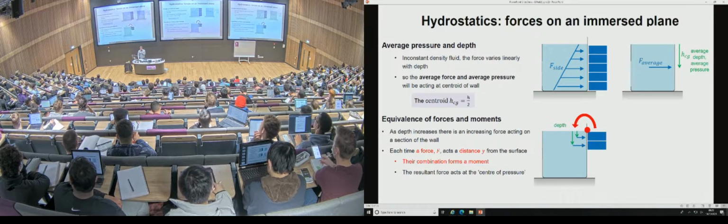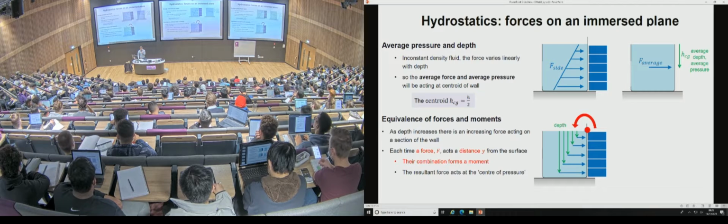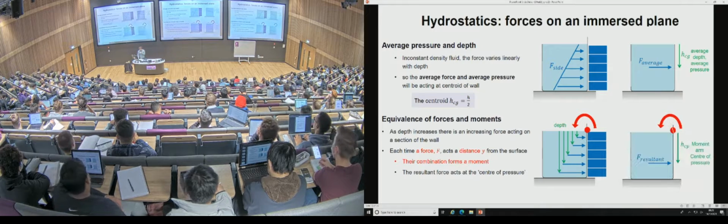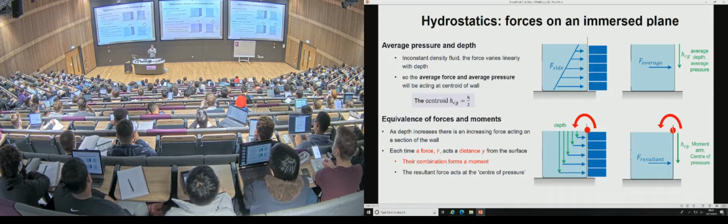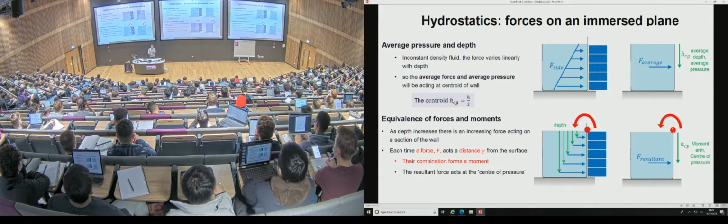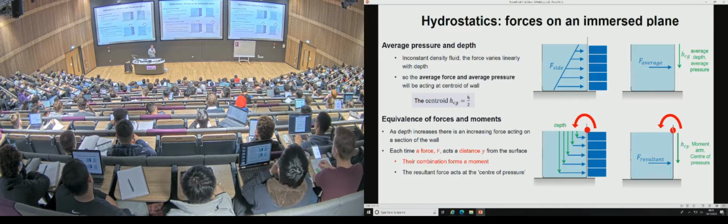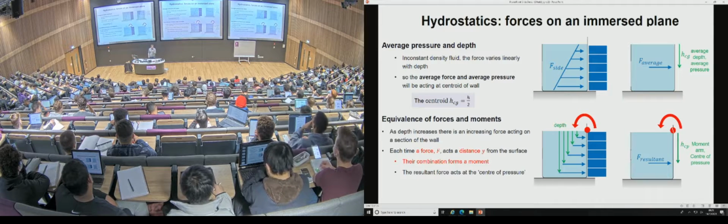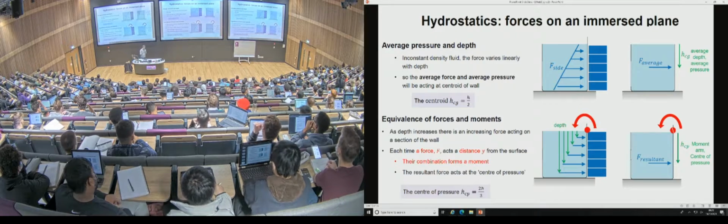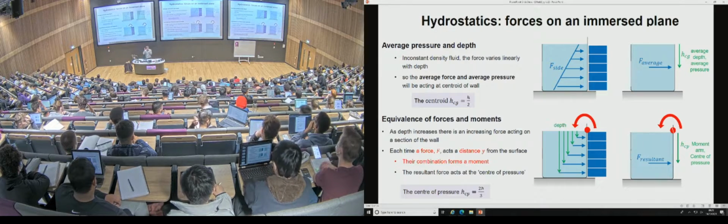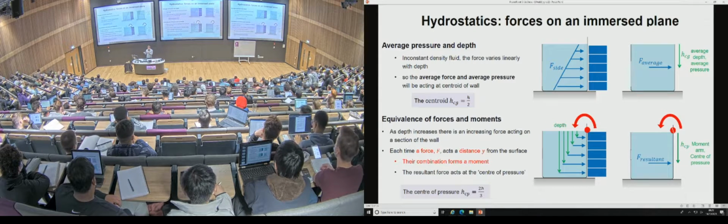So we take our elements, we times the depth by the force, all the way down, and then the sum of all of those is going to be the resultant force times by the moment arm, which is the center of pressure, HCP. And again, we're going to prove in a few slides' time that for a vertical surface, it's 2/3 of the height down from the surface of the fluid.